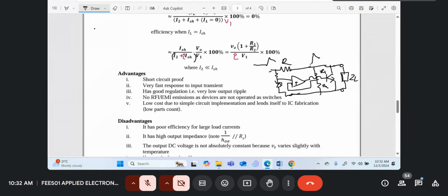You have transistors which are slow, for example the audio frequency transistors like the BC107, 108, 109, etc. Then you've got the RF frequency transistors, like the BF194, 195, etc. Then you've got the very fast ones, which can work up to microwave frequency, like the BFY90, etc. They can work up to gigahertz.